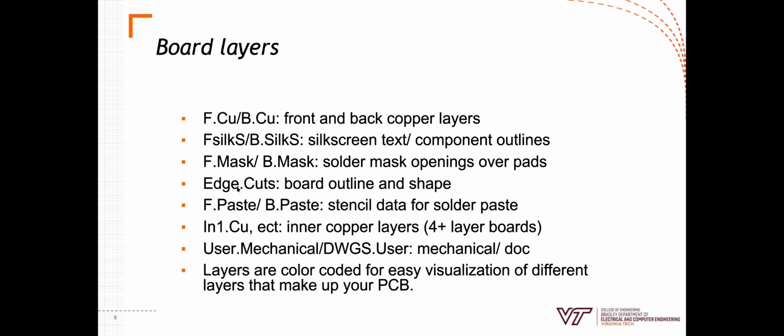Edge Cuts, this one's really important. This is your board outline. This is the actual shape of your board. You need to talk to whoever's designing STEP files for your project. If you're going to mount your PCB, then you need to know the specific shape that your PCB has to be.